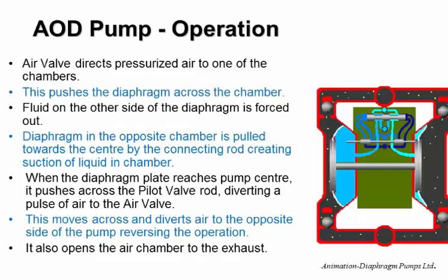Air-operated diaphragm pumps, those are very popular, and we can see how this works here. Now, it's kind of like a diaphragm plunger pump, isn't it? Except now we've got one plunger and two diaphragms here. So we're shown with the diaphragm here on the left in the forward position and the diaphragm on the right in the back position. So with the way this is shown, this is on the discharge stroke, this is on the inlet stroke. So we use compressed air.